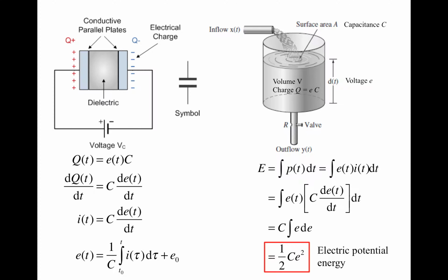I was saying that the capacitor and the inductor are both energy storage devices. So how much energy is stored in a capacitor? The amount of energy stored in a capacitor equals the temporal integral of the power, and the power equals the voltage times the current. For a capacitor, the current equals the temporal derivative of the voltage multiplied by the capacitance C. That's exactly this equation here.